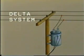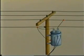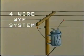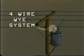But what can we do if the primary system is delta connected, ungrounded? Well, in this case, we must have a 2-bushing transformer. Both bushings are used to connect the winding terminals to 2 separate phases of the primary feeder. A 2-bushing transformer can also be used on a grounded Y system. Here, the second bushing is used as the grounded neutral connection.